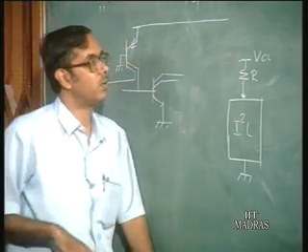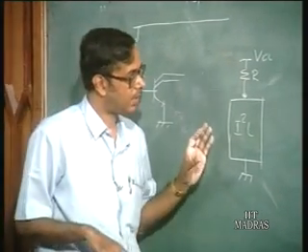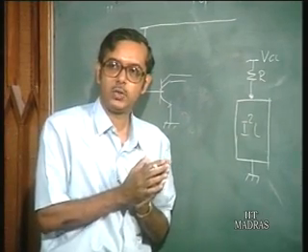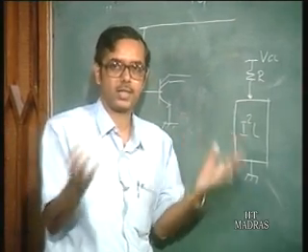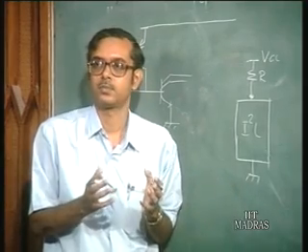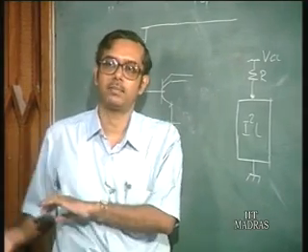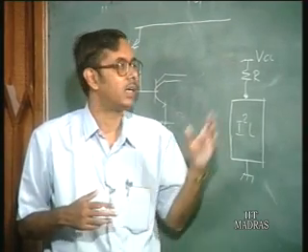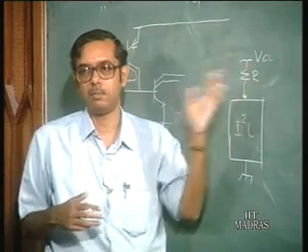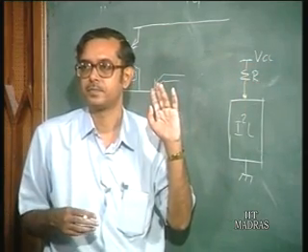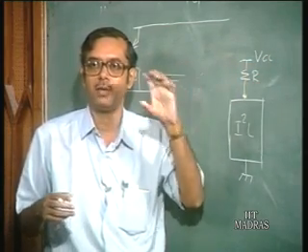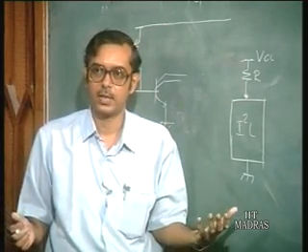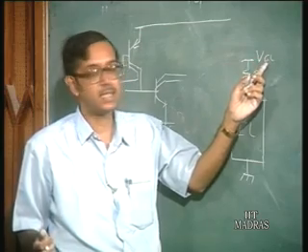But now you see, one interesting thing is that in many systems, you may have a system where not all the circuit is made out of I squared L. You may have part I squared L, the other parts may be TTL or some other logic family, and you may want to have a common power supply voltage, that is, a common power supply which is driving the different parts of the circuit. Now, this VCC may be 5 volts.